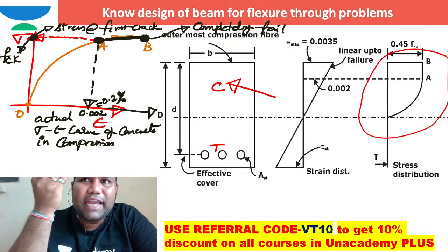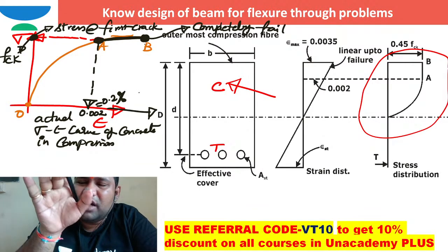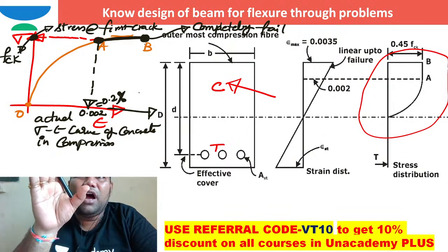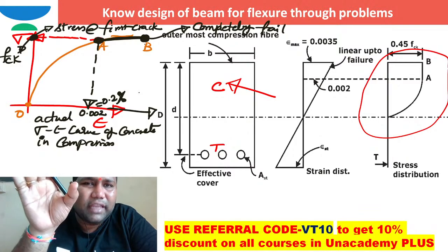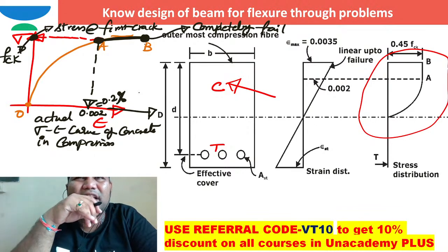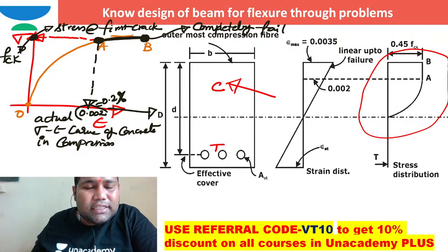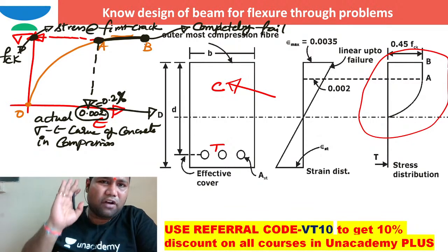So generally, if you take any traditional concrete, I am not talking about special concretes, of any strength, maybe M300, M400, M500, M600, M1000 also, made by traditional concrete without addition of any polymers or any other things, even if it is M20 or M30, the first crack in concrete in axial compression is initiated at a strain of 0.002, right? That is the constant value for any grade of concrete.